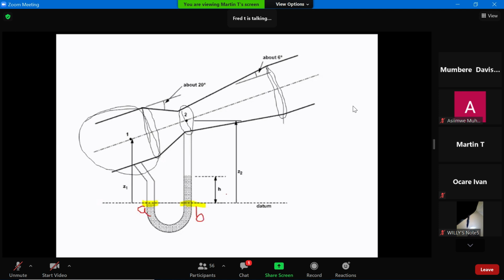Yes, so this goes with the manometric fluid because this is the depth. This depth is for a manometric fluid, so it's H rho_man G. Then plus rho G (Z2 minus H), plus Z1 minus H. Yes, then that's it: rho G (Z2 minus H).